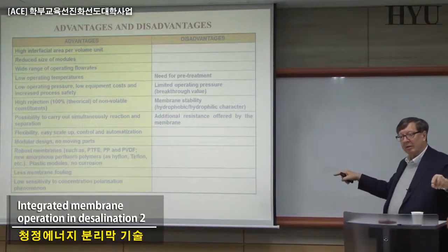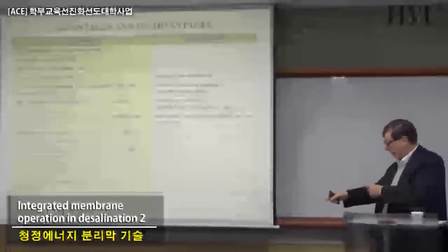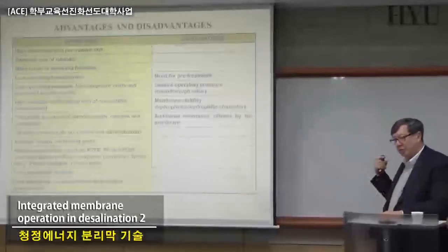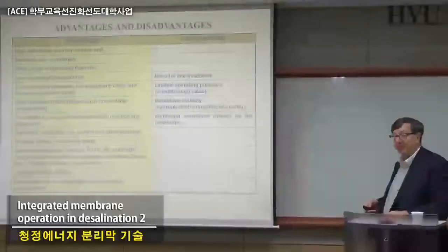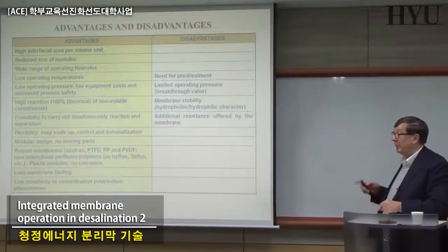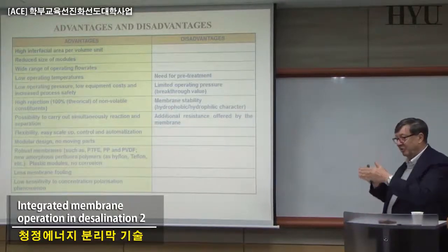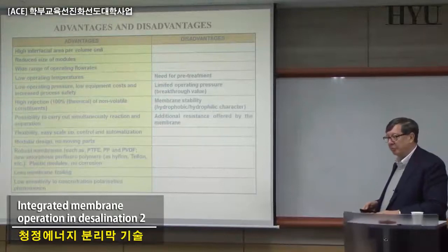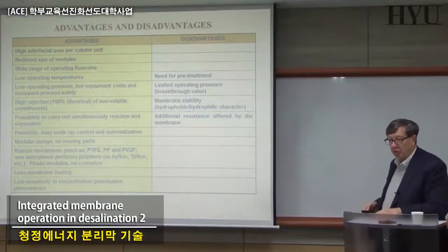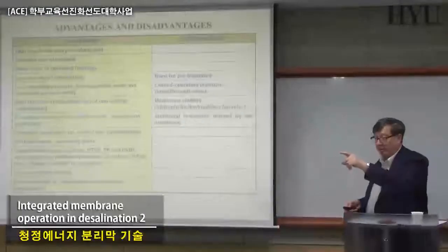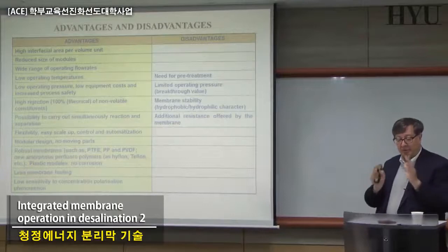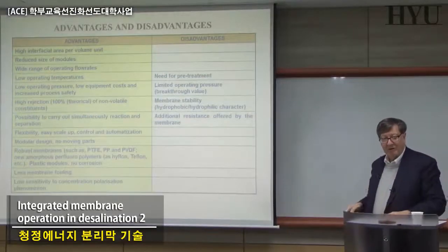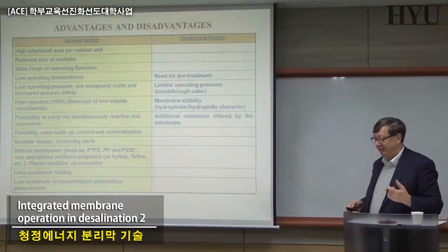Statistically, you always have this kind of distribution, the Boltzmann distribution, which means that if you want to have an application for ultrapure water for the electronic industry or for injection in your body, with the membranes existing today, we have a problem. We have to find a way to prepare, for this kind of application, a very, very sharp morphology, pore size distribution. Not easy. Everybody is working on this. Some of you are working on TIPS, producing these membranes, because in TIPS, in principle, you have a much sharper pore size distribution than traditional NIPS.